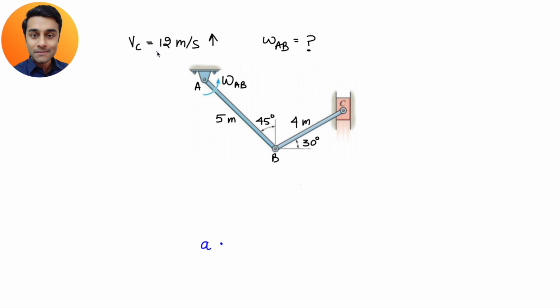And it is given that this velocity has a definite magnitude, that is also known. So we can draw a definite vector having both ends. It is not like the other vector AB, velocity of B with respect to A. Here we cannot put an arrow on the vector. We cannot end the vector at this point because we don't know the magnitude of omega. So we cannot define our omega's value. But since the question has given you a direct magnitude for C, we can define a definite vector like this.